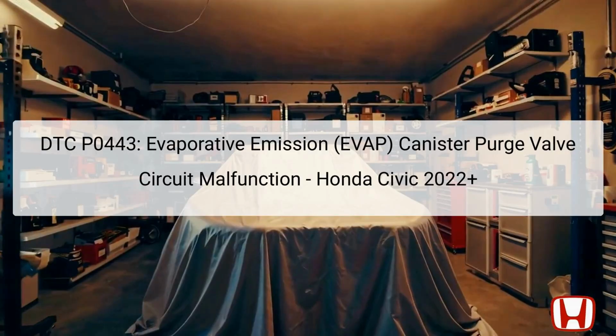The DTC P0443 refers to a malfunction in the evaporative emission control system, specifically in the Canister Purge valve circuit. This component plays a crucial role in managing fuel vapors from the fuel tank to reduce emissions and maintain overall engine performance. Located in the engine compartment, the EVAP canister purge valve is responsible for allowing the engine to draw in fuel vapors from the charcoal canister when conditions are suitable.